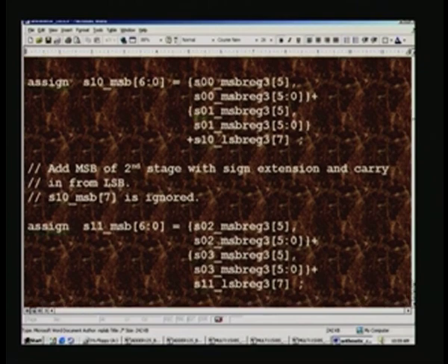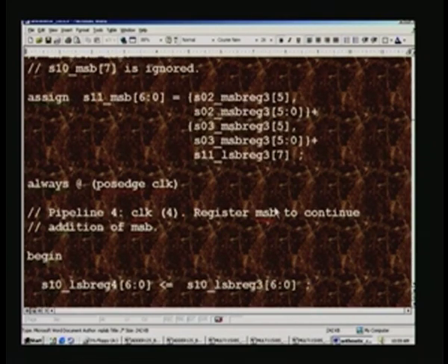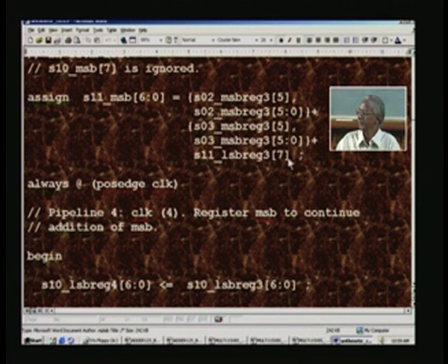And next what we do is, we have MSB here sign extended, and this is also MSB once again sign extended, and there is also one carry resulting from the previous one. Earlier what we have seen is for first output is S10, and here we see for S11, it is exactly same thing as that, and now we have added LSB as well as MSB.